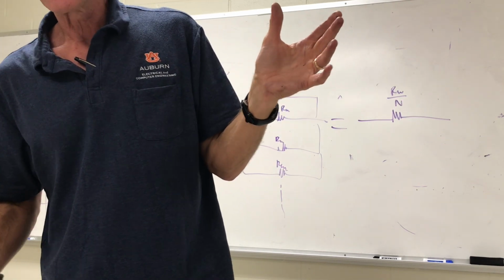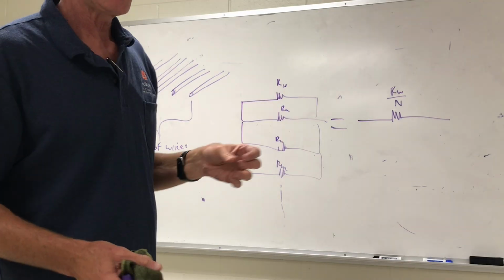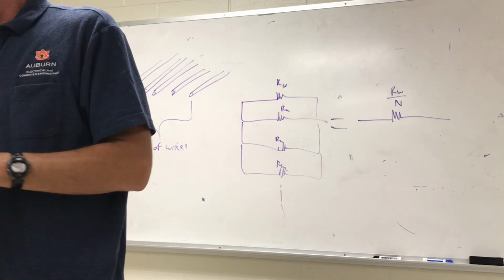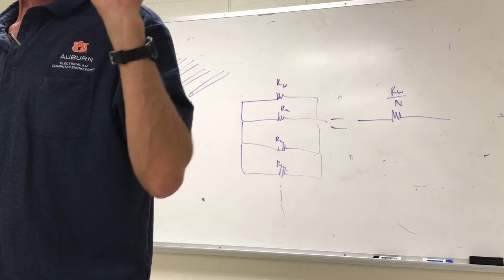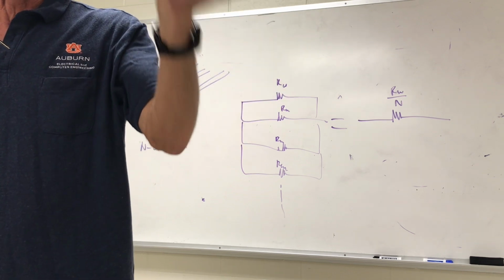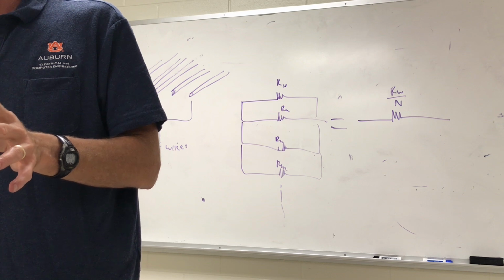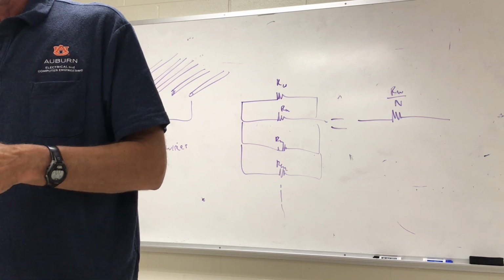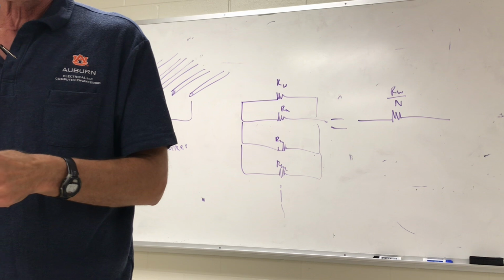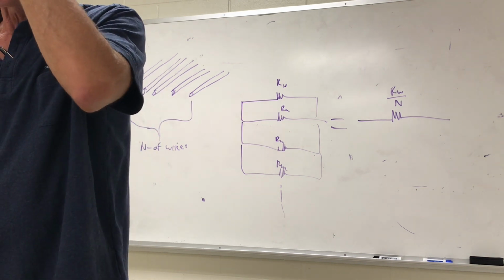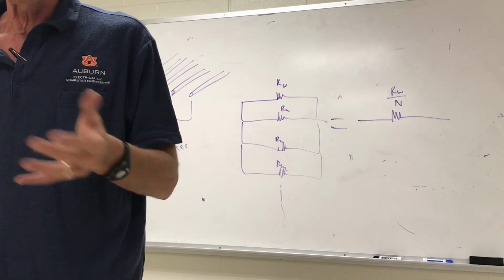So when you get these wires, I'm going to give you data sheets that are actually real data sheets, and they'll have a certain gauge wire that you're going to have to find out the diameter and then get the radius of the wire, and it will be in mils, so you have to convert that to meters. And then you're going to figure out how many are in parallel, and you're going to figure out either the resistance or inductance or impedance of the wires.